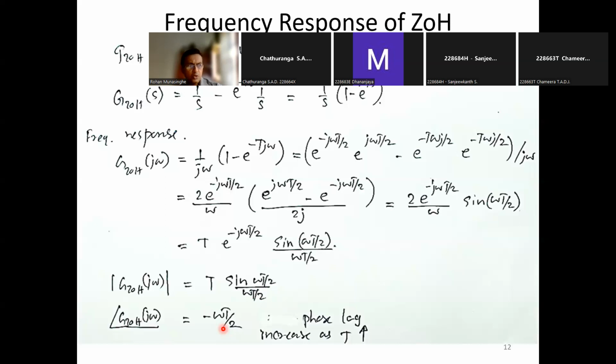Okay. So I think we saw this earlier also. Every time you get a signal through a zero-order hold, you introduce T by 2 time delay. Now there you can see it very clearly, T by 2. This is not a surprise, or a significant derivation either, but very interesting because we manually saw the delay of T by 2, and the moment you multiply it with omega, you convert it to radians.